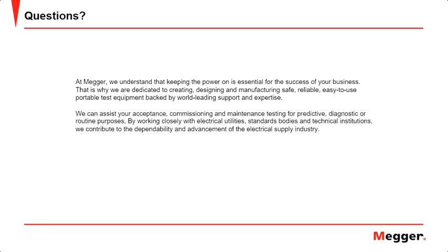Again, it's sometimes best to wait 5 years before measuring, if you're going to take data, because that allows the cable to absorb moisture and the water trees to form. If you're doing an installation test and you see those, you know that from the manufacturer or from transport, there is moisture ingress within your cable.